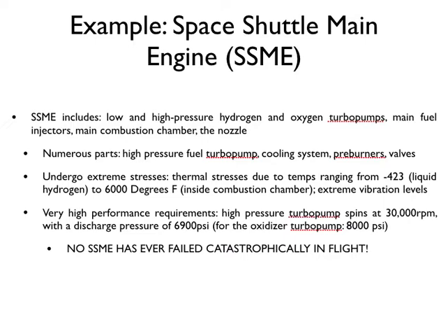And so this particular system has a huge range in its requirements for temperature. It also has very high performance requirements for the RPMs of the turbo pump, which is 30,000, and the pressure of 6,900 psi. So it's a pretty extreme environment that this thing is operating in, and it's very critical performance as well. So that adds to the challenge.